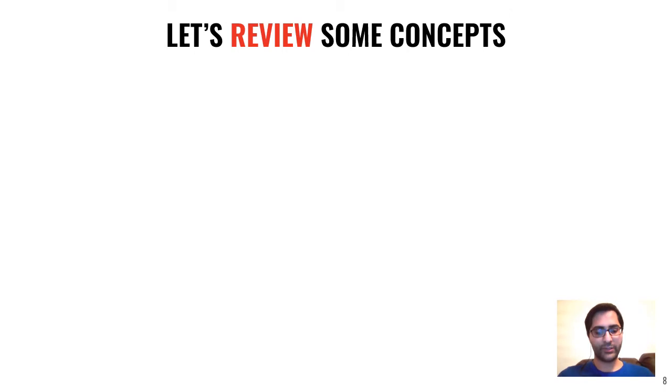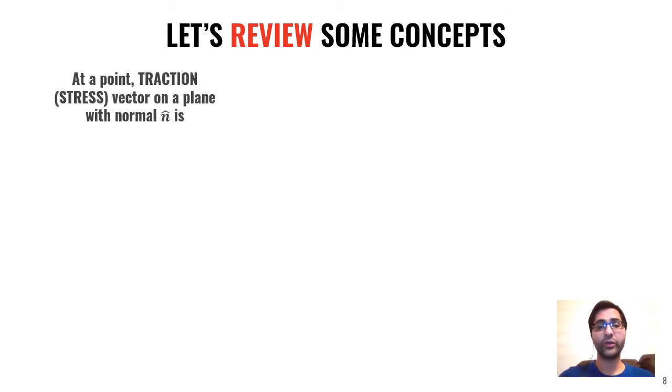Let's review some concepts. First, we talked about the traction or stress vector on a plane with normal n at an arbitrary point. We showed that we can write Tj of n is equal to Tj of ei multiplied by ni.